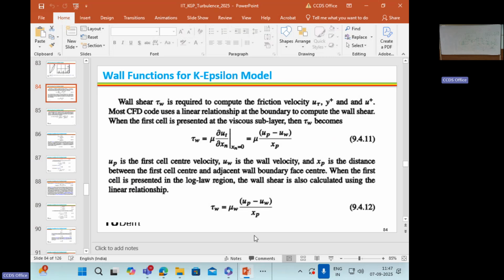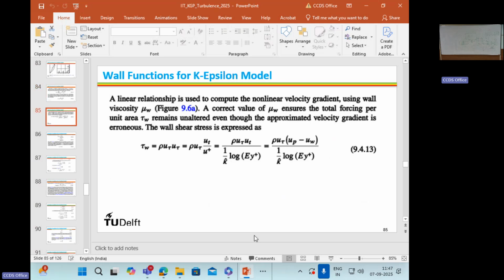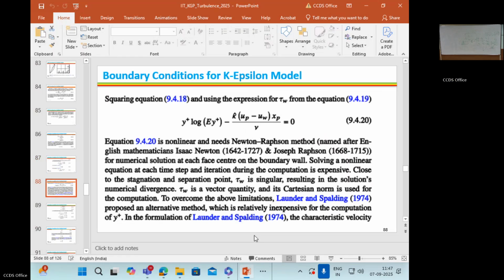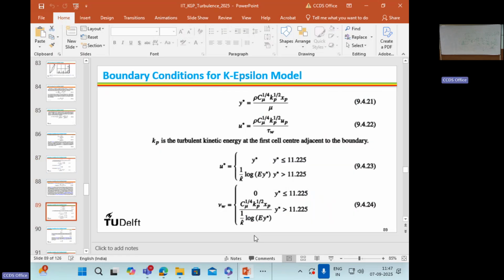So wall function doesn't change the velocity explicitly. It calculates based upon the fitting function. It calculates a wall viscosity. Save it at each face center, not cell center. It saves the wall viscosity at each face center, right? For each face value, you are calculating the shear stress.